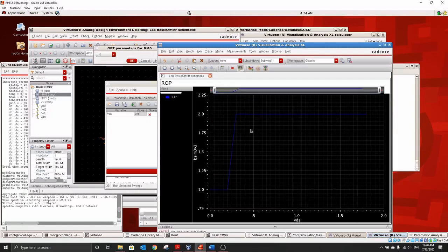What one could do is, by making use of the cross function, evaluate the minimum voltage, or you can use the horizontal axis and move it to 2, and if you just hover your mouse, it is almost closer to 300 millivolt, and that is the reading that you could see over here. So the VO minimum that we currently have here is 300 millivolt.